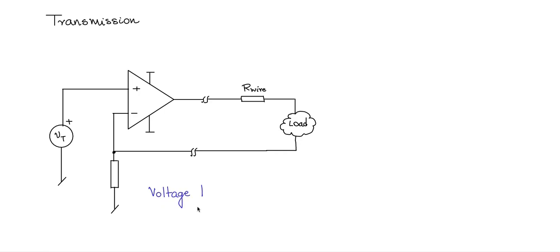Now this is the voltage to current conversion circuit. I will call this resistor R. This is the most critical component here. And because of the virtual short here, if this is VT, this is also going to be VT. I'll write this one, VT. And what is the current that is flowing through this resistor? It is going to be VT divided by R. That is current I.